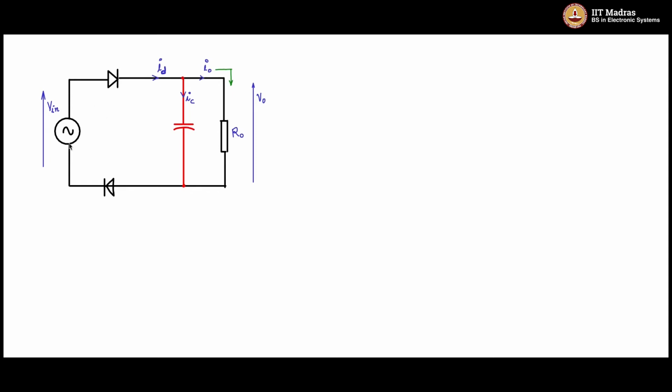So by drawing this diode, when the input source is positive, we will see the flow of current through these diodes in this fashion. Right now there is no change in the circuit and its operation except that we have added one more diode. But this diode is important because it will steer the currents during the negative half.